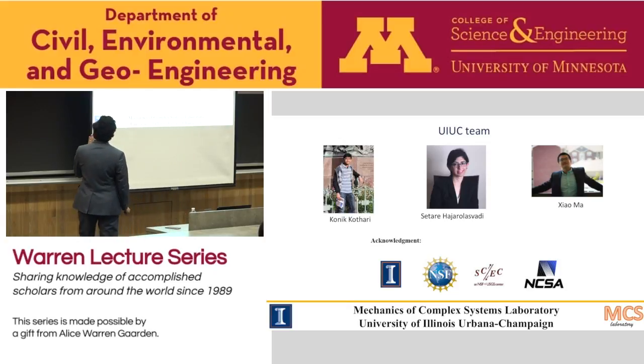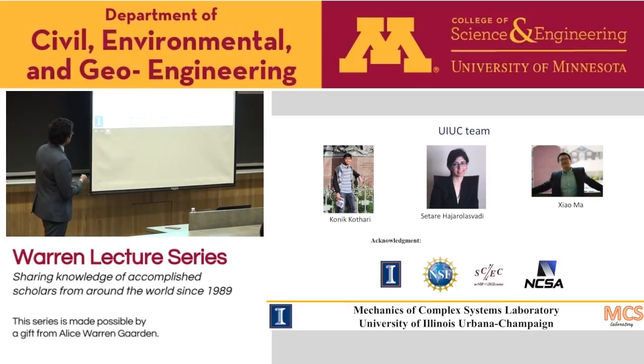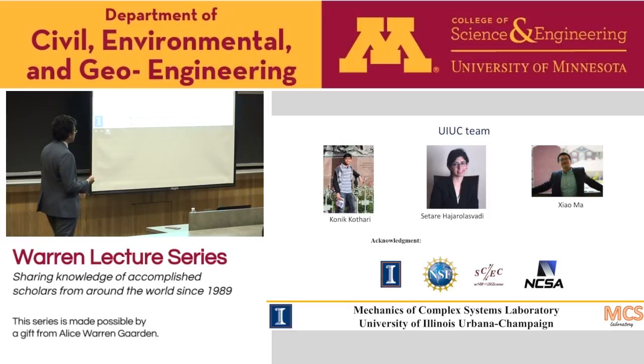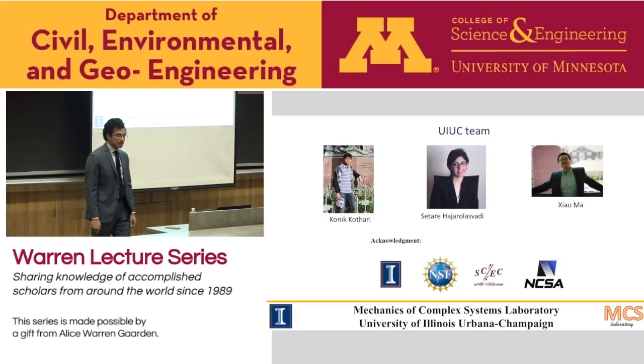So these are the conclusions. What I would like to say is now we have the ability to hopefully embed our high-resolution fault physics into elastodynamic models and couple them to allow the propagation and initiation of complex shear bands. We can also start looking at competition between dilatancy and thermal pressurization, which people find difficult to explore experimentally, and there are not many models on that. And of course, if we are trying to do predictive modeling, then we need uncertainty quantification.